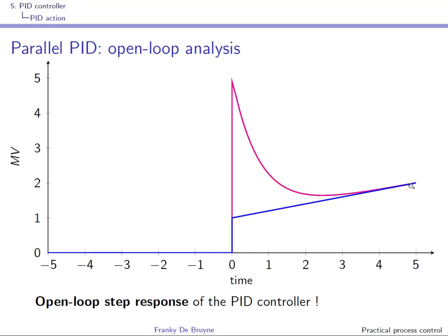So for a large t, what you have is only the effect of the proportional integral part, right? Because the derivative part is vanishing. And of course, proportional integral is the integral part on top of the proportional part, here shown in red, right? You integrate something that is constant, so on top of this proportional part you have something that is increasing linearly.